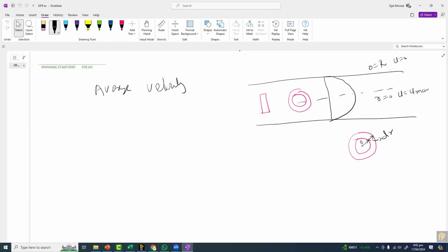Okay. So now let's say I want to find out the flow rate here. This will be dq, the volume flow rate inside this whole strip. And what is the area of the cross section of this strip? This area would be equal to the circumference into the thickness. If I open it, the thickness will be dr, and the length when I open the circle will be 2 pi r. So the differential area dA would be equal to 2 pi r into dr.